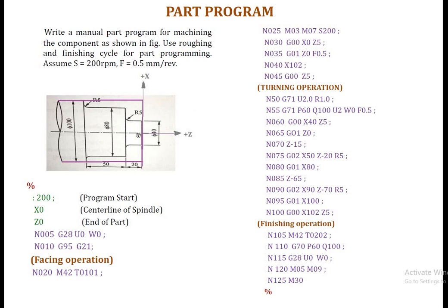So for 1 mm program movement, the tool actually moves by 0.5 mm. So here the total movement is by distance 102, that is the program movement, but actually the tool moves by 0.5 into 102, that is 51 mm distance. This is the diametric programming mode.